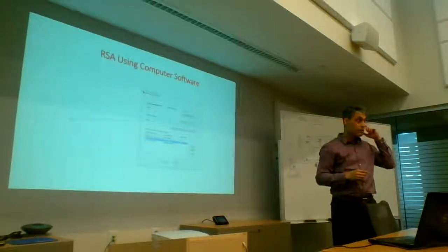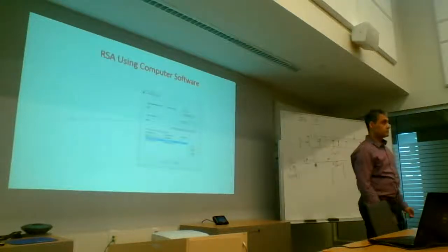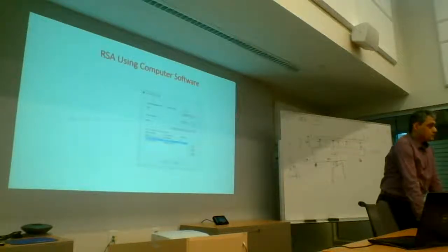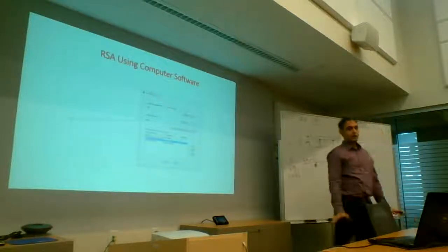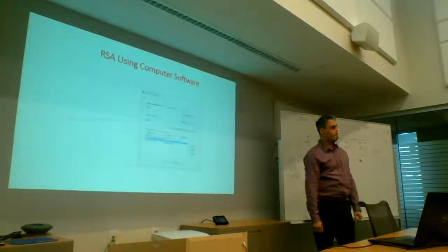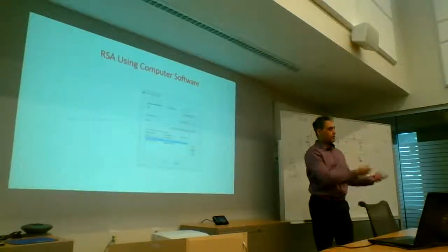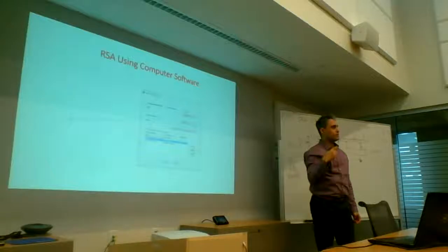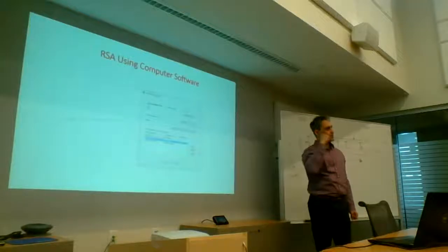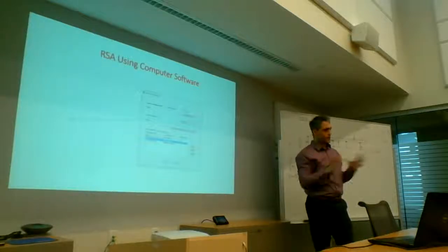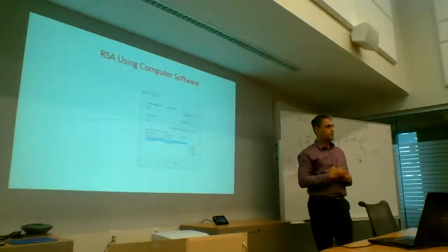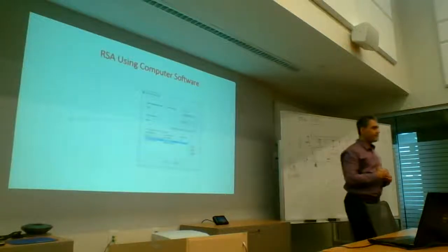And we can put the mass. Yeah. Or you will calculate the gravity load, or the dead load, or we consider some portion of live load. So in our code, we're only looking at the dead load at this point. When you're exciting the bridge, you're only looking at the dead load. It has some clause where it says, after your earthquake, account for your damage and make sure that it can take 50% of the live load on it. When I get to the pushover, I'll talk about it a little bit. But when you're exciting to come up with your frequencies and your inertial loads, you're only looking at the dead load of the bridge itself, no vehicles on it. So when I calculate this period or frequency, I will only consider the dead load.